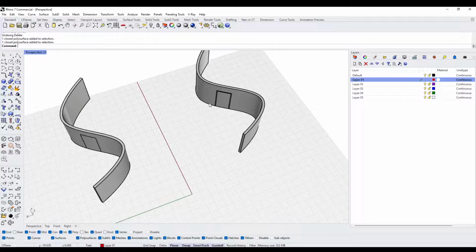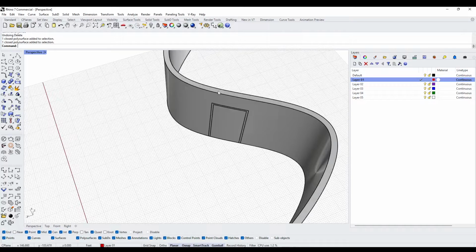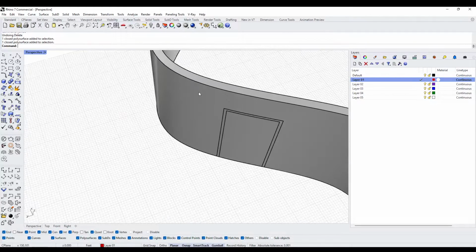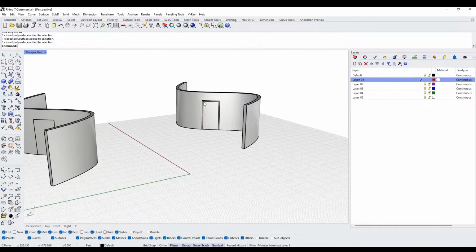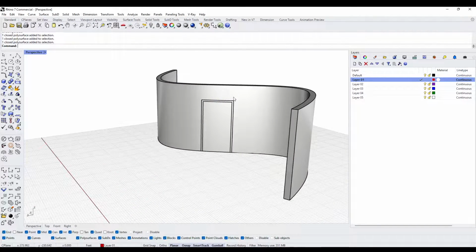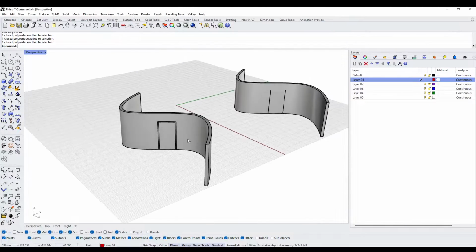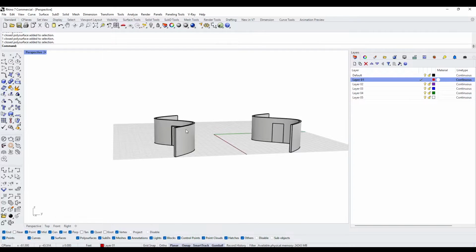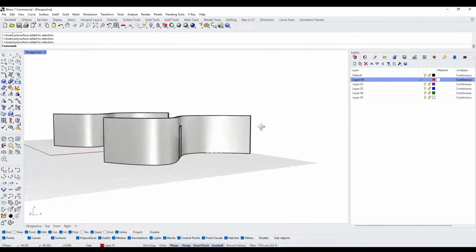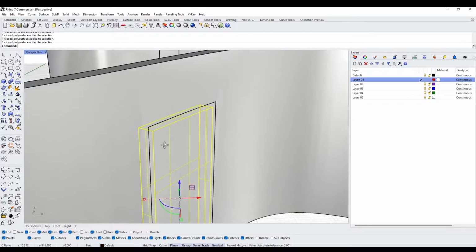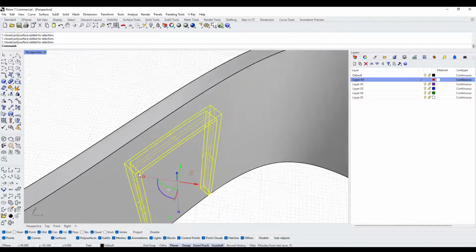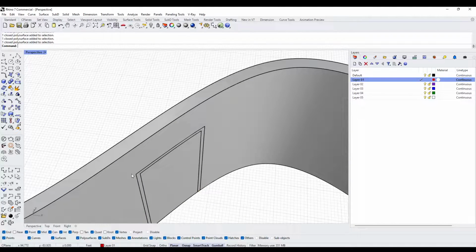The reason why is because if you take that segment and you cut it off and you extrude one side and the other, it's going to be really difficult to recreate the segment that's left over. And with it being curved, it will also create a crease, and it won't look as good as this, which is pretty seamless. And this is a wall that is extruded up perfectly. So that is one of the advantages of this one. The only thing that would be a little bit strange is that this technically isn't a line. It's part of a curve.